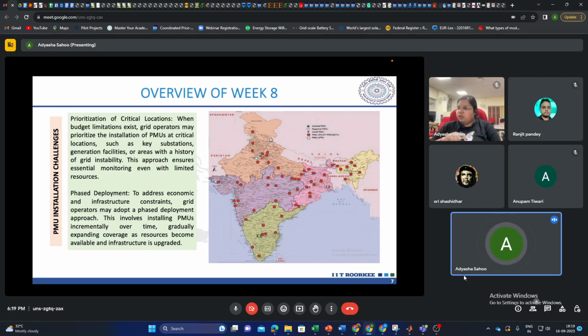So ideally, we take resistance and reactance as constant when doing our power system studies. But in actuality, if you go to the Jammu Kashmir region, where we have extreme low and high temperatures, this R and X will be different from what they are on paper. So this mismatch will happen. We have voltage values on pen and paper, but they may not necessarily match what is at the actual location.